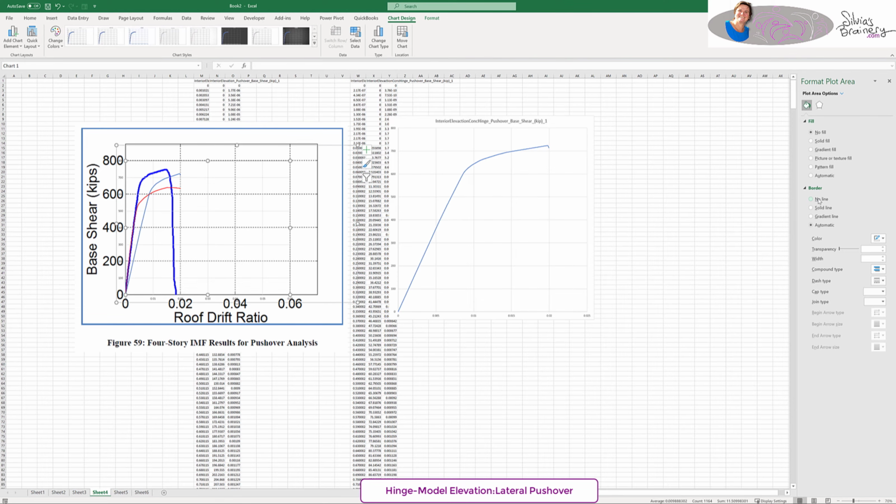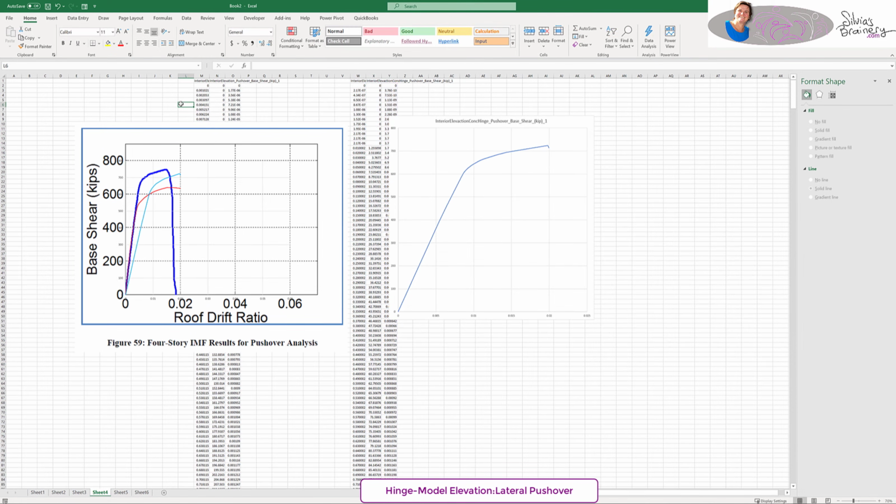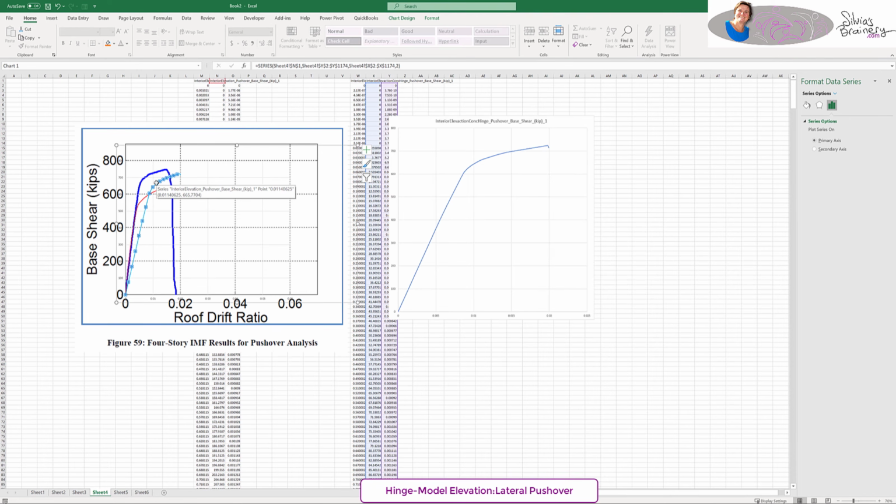So here's the results that I get for this case. I think they're excellent, that I get the same base shear. I think the stiffness properties, interestingly, I have the same period, but the pushover behavior is different. And I'm going to try to do a couple of things here to see if I can get closer to their model, but I don't know what they did. So I'm going to see what can I do to stiffen the system?